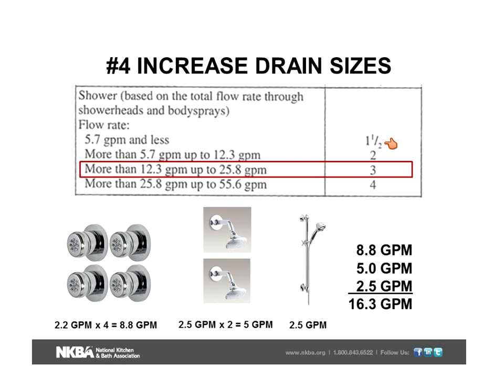So taking a standard tub out, replacing it then with maybe a 2-person shower, you're going to be all right until you start adding these shower heads. Now let's take a look at a combination we have down here, 4 body sprays. Now these actually put out 2.2 gallons per minute per spray for a combined 8.8 gallons per minute. 2 shower heads that could be running at the same time.